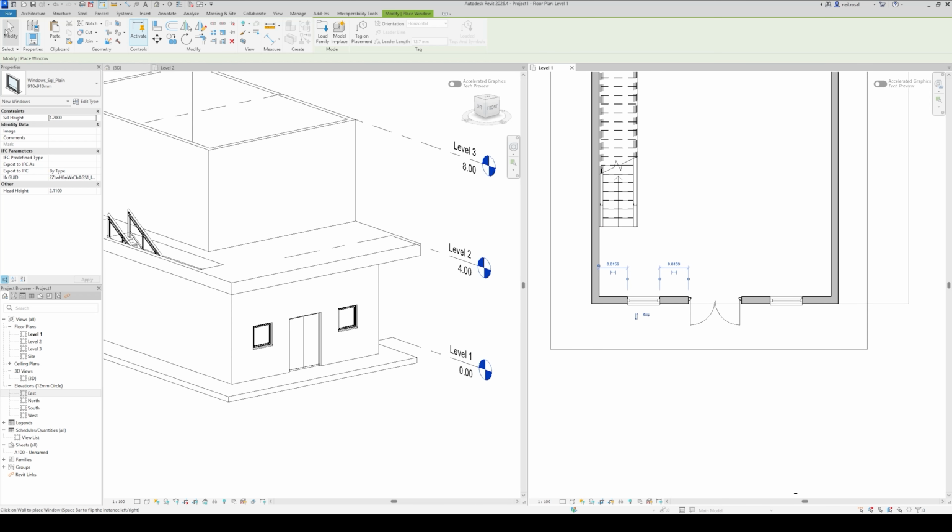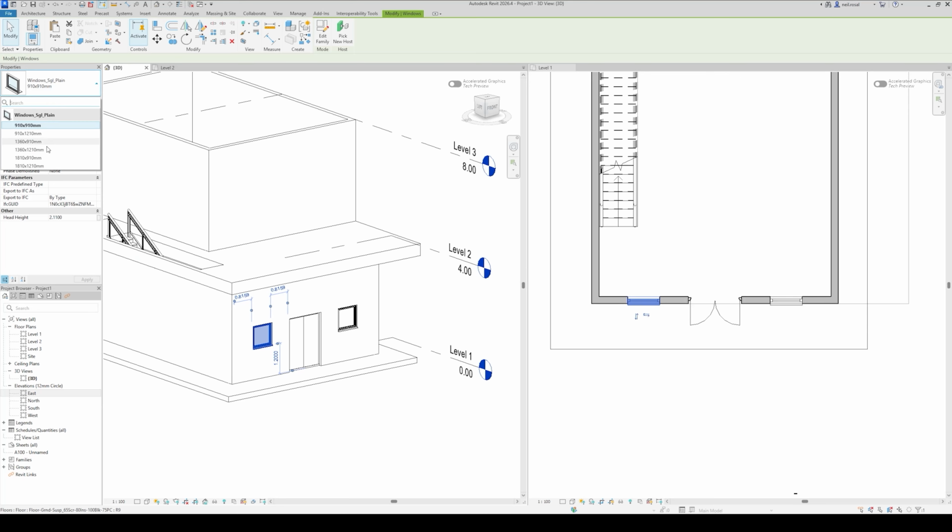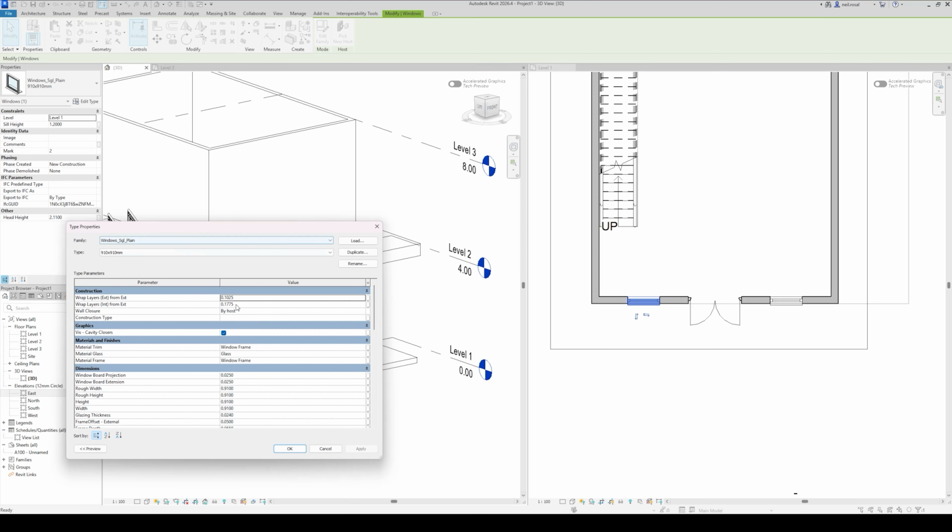I can have customizable windows, like my walls, through these selections of windows. Maybe I want that type of window. Actually, maybe I want to create my own window. So I'm going to duplicate this group, this CAD block, and tamper with its measurements. I'm going to duplicate it and name it maybe a 2-meter window. That'd be cool. By 0.91.